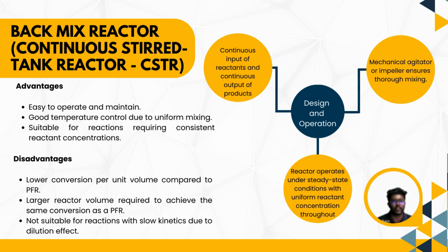The first one is it is easy to operate and maintain. The second one is it provides good temperature control due to uniform mixing. And finally, it is suitable for reactions requiring consistent reactant concentration.